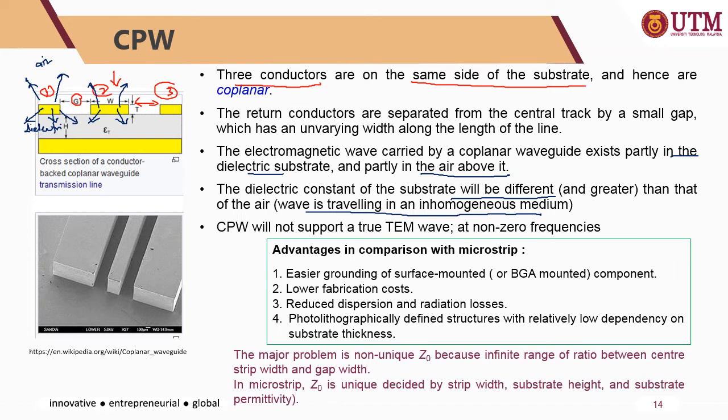And in terms of the mode, CPW or the coplanar waveguide will not support the true TEM wave at non-zero frequencies.